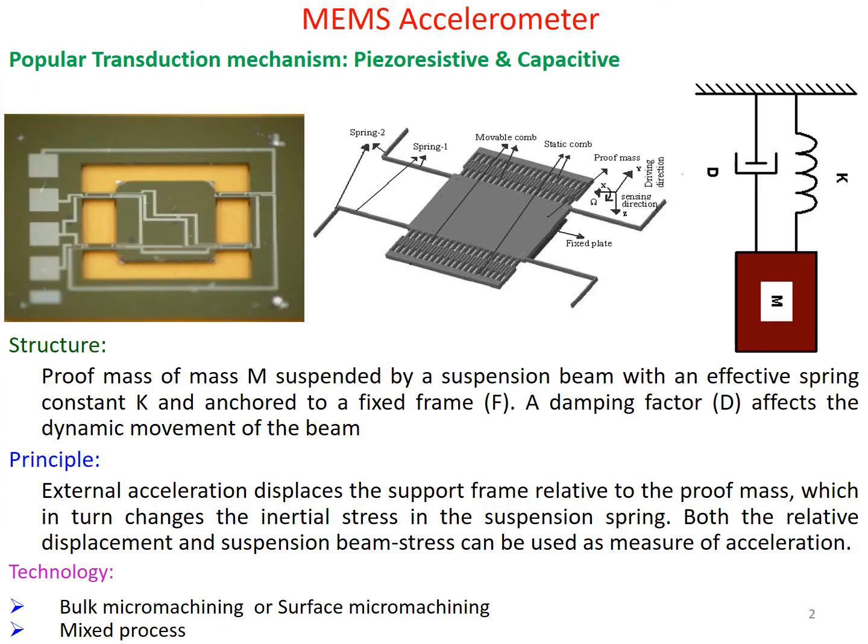As we have already told the basic principle of the MEMS accelerometer, that is nothing but a mass spring damper system. As you can see from this particular model, and in the last class we have told that we can write the second order differential equations or the transfer functions for this model, where the resonant frequency, the undamped natural frequency and the damping ratio are the important parameters. Now that accelerometer is also one type of sensor, and what is its job?